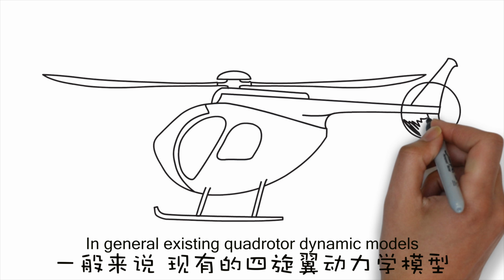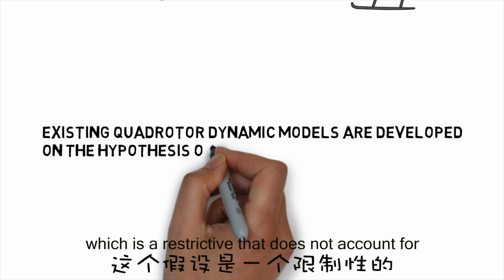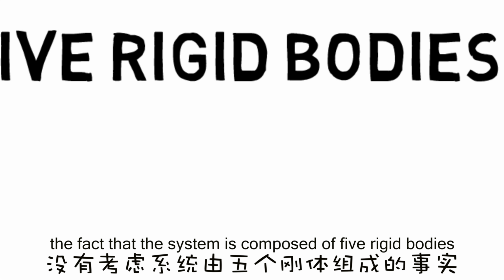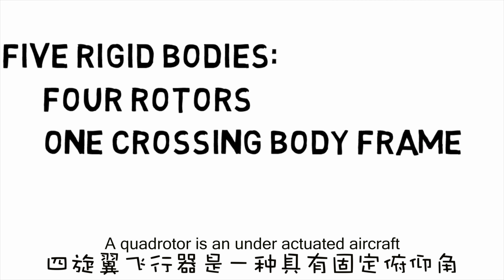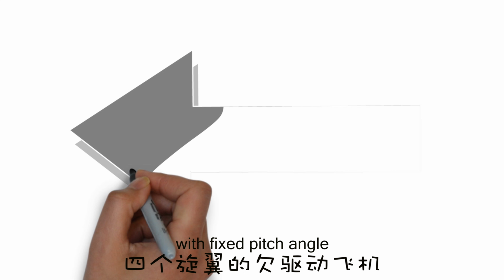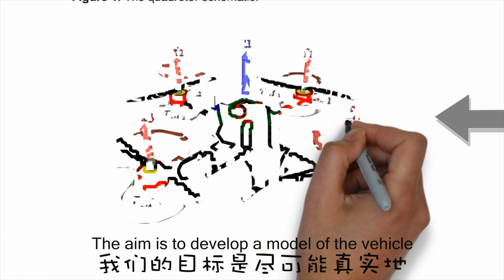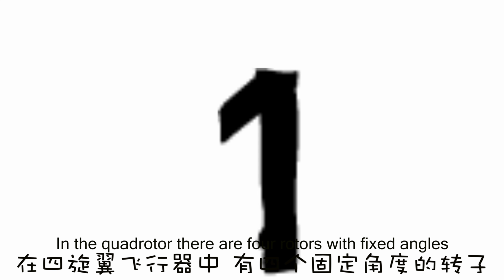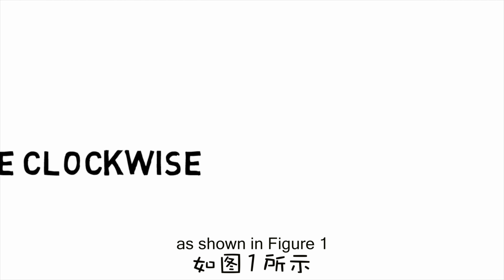In general, existing quad-rotor dynamic models are developed on the hypothesis of a unique rigid body, which does not account for the fact that the system is composed of 5 rigid bodies: 4 rotors and a crossing body frame. A quad-rotor is an under-actuated aircraft with fixed pitch angle, 4 rotors, as shown in figure 1. The aim is to develop a model of the vehicle as realistically as possible. In the quad-rotor, there are 4 rotors with fixed angles, which represent 4 input forces that are basically the thrust generated by each propeller, as shown in figure 1.